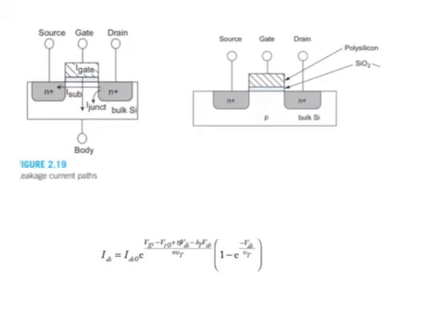The principal effect is due to subthreshold leakage, that is the leakage of current from drain to source. There is a second source of leakage from the gate to substrate, and this leakage comes from tunneling of currents through the oxide layer, from the gate through the oxide layer. The third source comes from junction leakage, that is from the N plus of the drain to the bulk, and this actually arises from the reverse bias diode currents that are leaking, and the reverse bias diode is formed between this N region and the bulk region of the MOSFET.